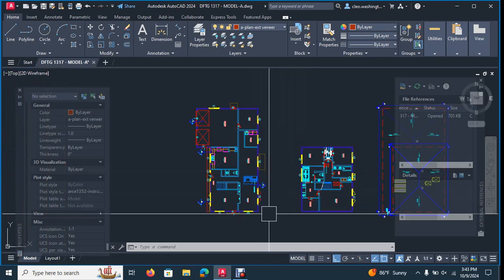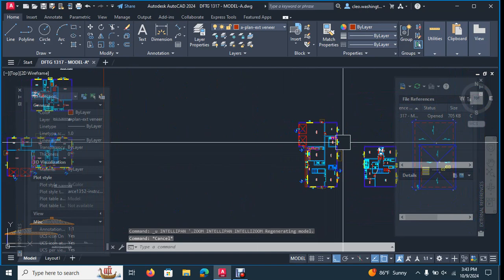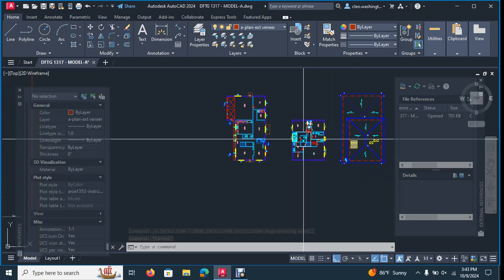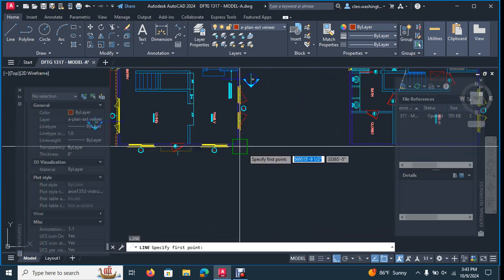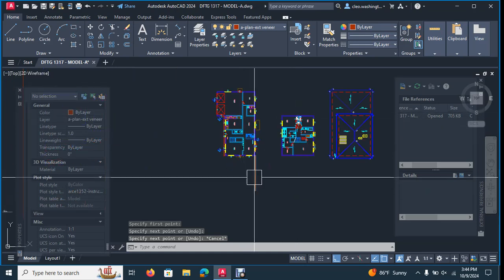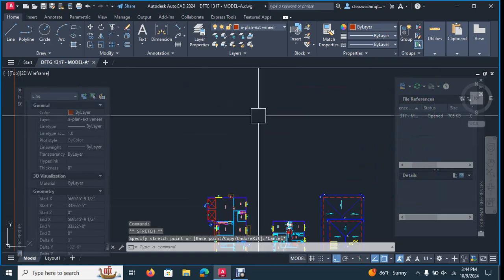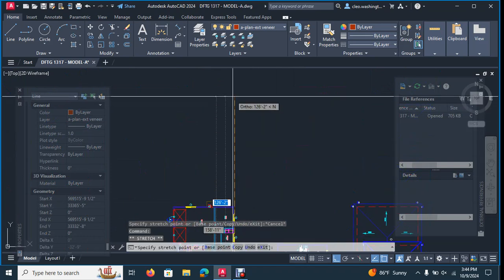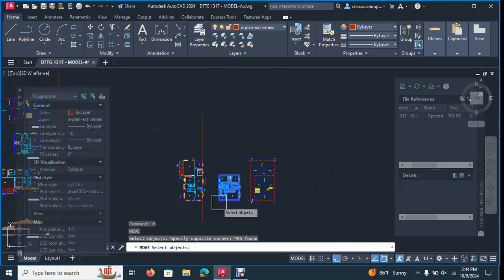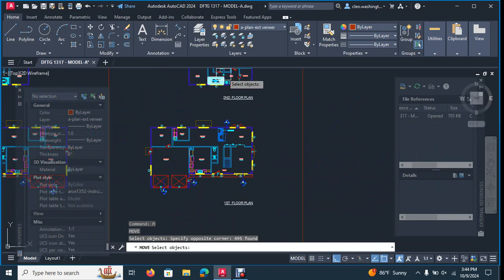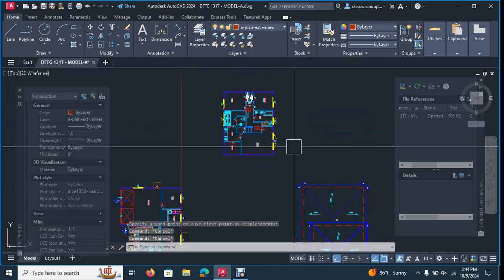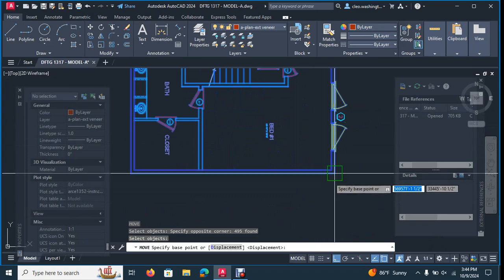Yeah, so what you want to do is make sure that you go ahead and align these, right? So this is your second floor. So you want to just draw a line down, okay? Because what's happening is you're going to be projecting everything down. So take this line and pull it up. Just grab the grips and pull it up. And then you're going to move this guy up, okay? Yeah, you got all your stuff in your second floor there. And let's take this guy and move it up. Take this guy and move it up, move it over.